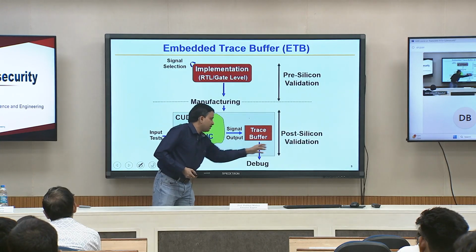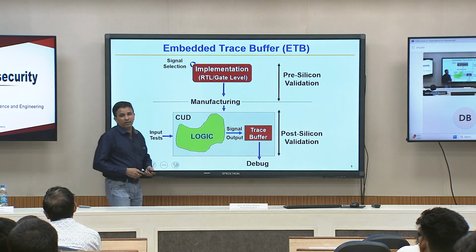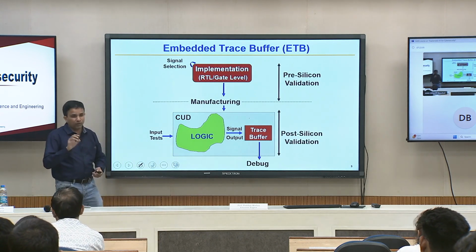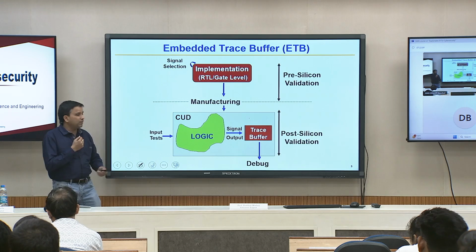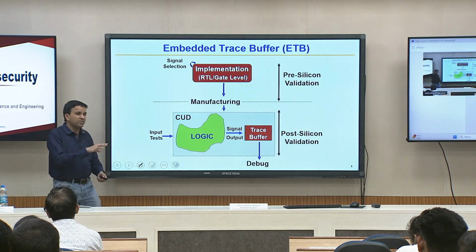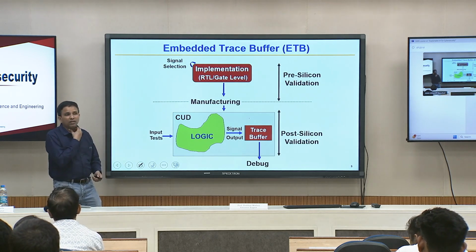When I run my program, you can run your program. I tell it that you only track my XYZ variable, right? Then they will map those XYZ variables to those registers, some of the input ports of this trace buffer, and then you will overwrite after every 1024 clock cycles. So software programmable trace buffers you will be able to control. Hardware programmable ones you have to dump, you have to stop execution and that kind of stuff. So that is not like real time malware detection.